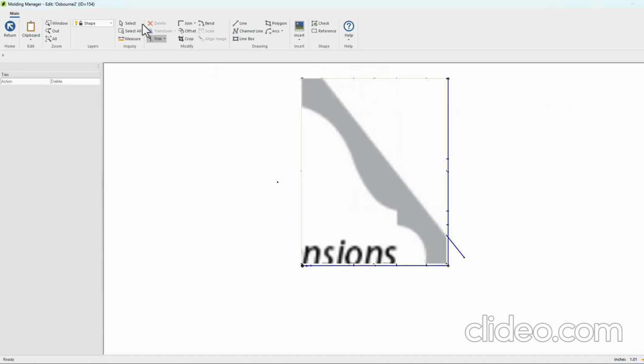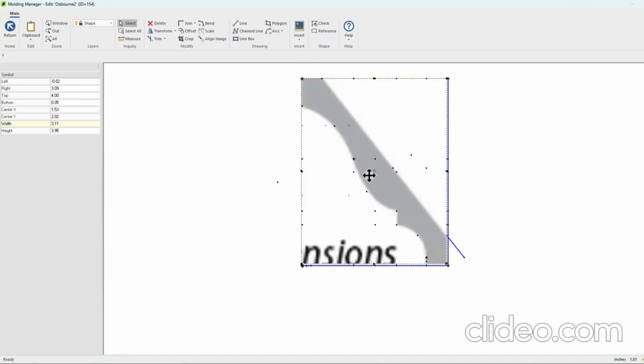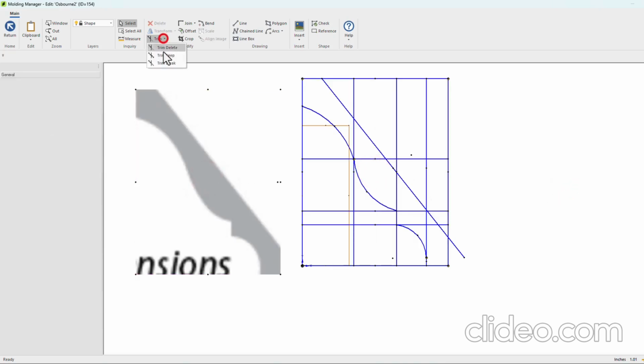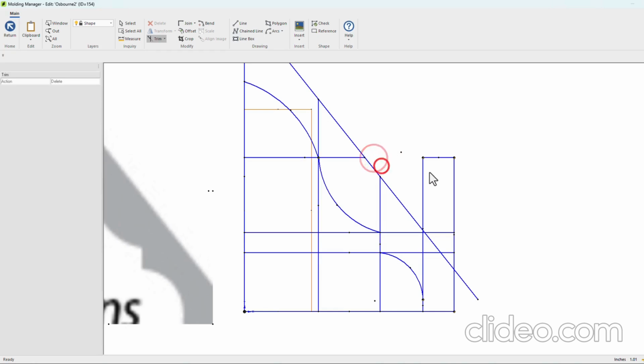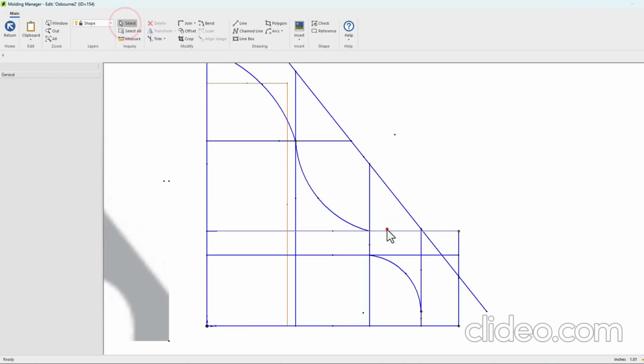Now, it looks like my image is kind of causing problems, so I should maybe just get my image out of there. Just set it off to the side, and then go trim delete. Then you can just click on the lines one by one, and notice how it only deletes toward the intersection. So that's the difference between trim delete and the select tool, because the select tool will select the entire line all the way across, which I don't want to delete. That's why we're using trim delete, so it only does the intersections.